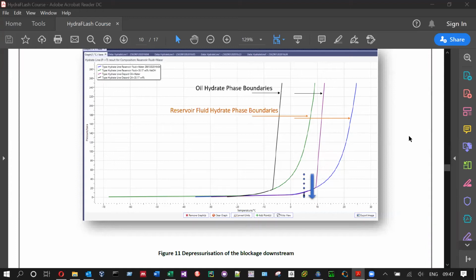Thank you. If it is a vertical well, a vertical condition, methanol is not as efficient as MEG, because after melting hydrate, methanol comes on at the top of the water and loses contact with the hydrate. MEG is better, okay?